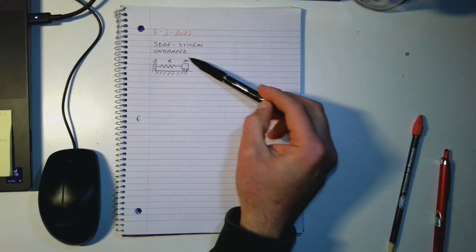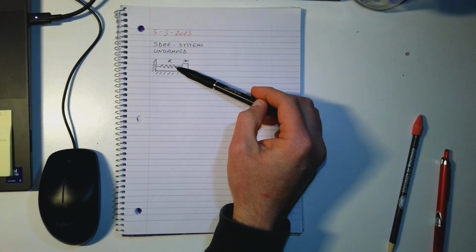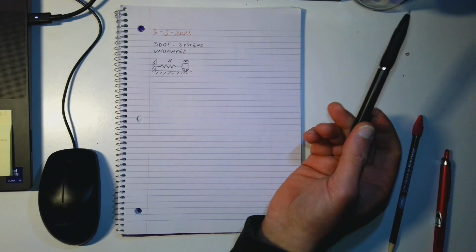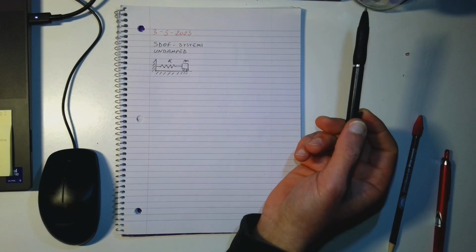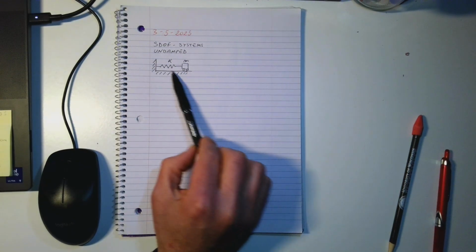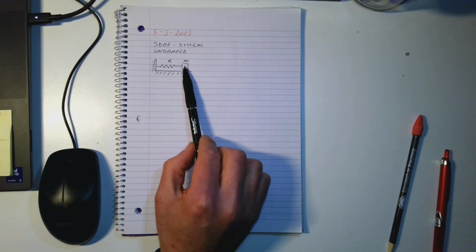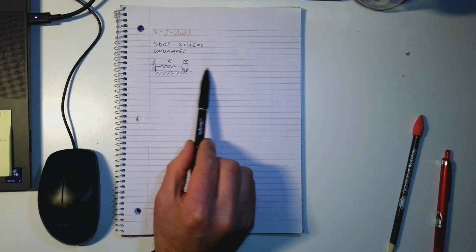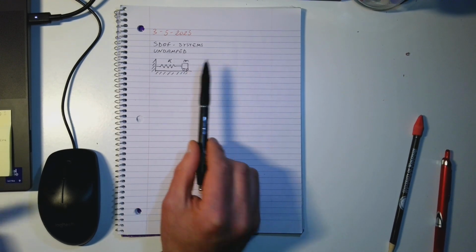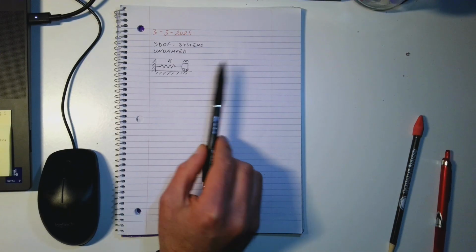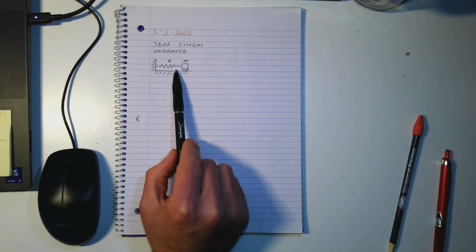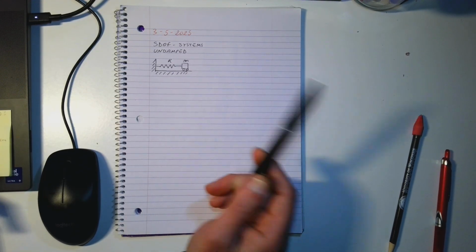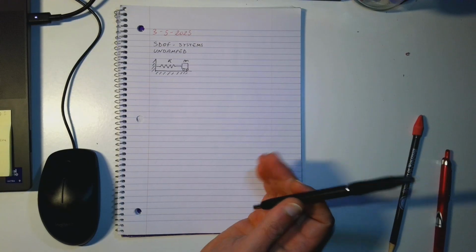If you remember, once we looked at this system, the very first thing that we did was to write the equation of motion. To write the equation of motion, we used the force method, which means we look at all the forces that were applied on this block. In this case, we look at the motion that occurs in the horizontal direction. So of course we look at the forces in the horizontal direction. The forces in the horizontal direction for this one are the force of the spring and the inertia force, which is basically the product between the mass and the acceleration.